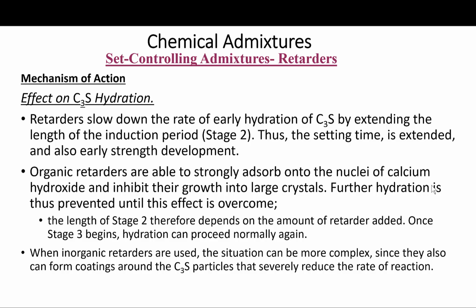The length of stage 2, as a result of that, depends on the amount of retarder added. But once stage 3 begins, hydration can proceed normally again. So remember, this is the effect on the C3S hydration by extending the induction period.